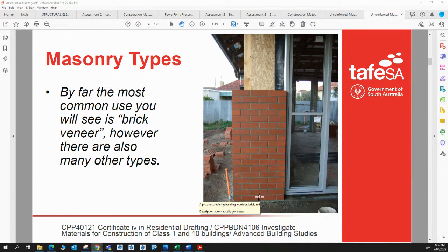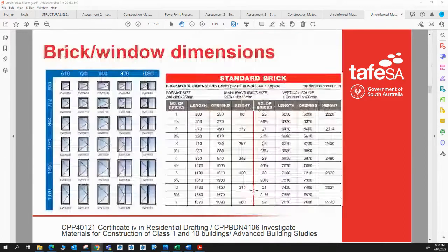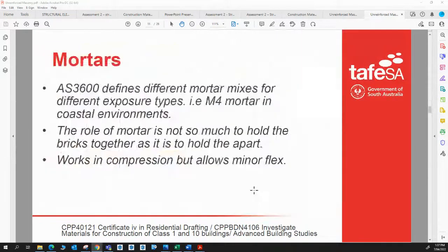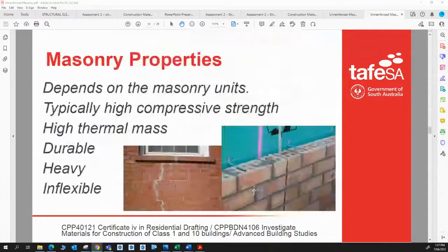They're these little weepers, they're called, that you go along and push into those weep holes afterwards, that still allow water to come out, but will stop embers going up into there. So that's the main consideration with using brick in the bushfire prone area.